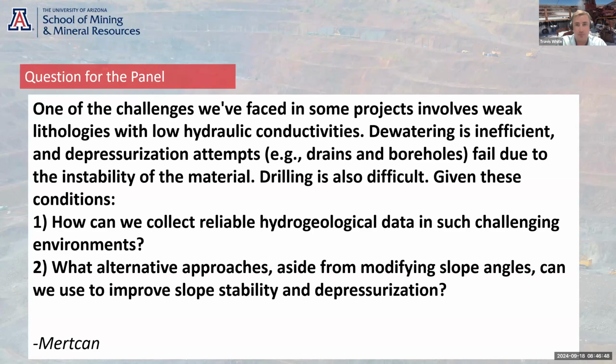There's actually another question I saw in the Q&A about installing VWPs through casing. So I'll jump to that now, Joel, but the answer is yes, you can do that, as long as the permeability of the casing is higher than the permeability of whatever you're measuring. So as long as water can get in, once you've grouted it up, the VWP can work, and we use that as standard practice, especially in these environments where the holes collapse or it's difficult to drill. When you're drilling inclined especially, this is a nuisance. So the use of casing and then installing VWPs through that is beneficial.